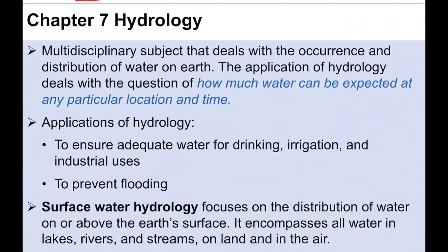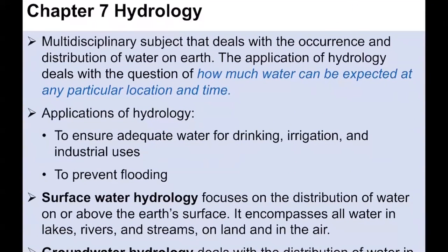So now we can focus our time on the hydrology, all right? I know that you guys did the hydrology lab last week, right? That is mainly about the conductivity, basically how much or how fast the flow can go through a certain filtering media. You can use different types of sands to find out that the water is going to flow quicker, or the flow rate is going to be larger, if you're using a material that has a larger porosity, right?